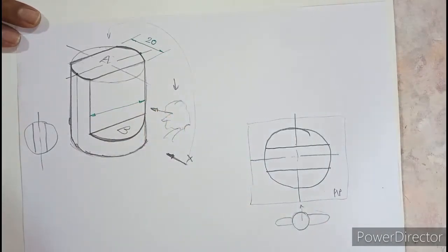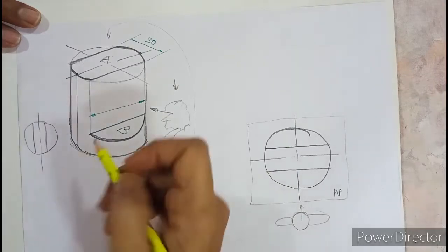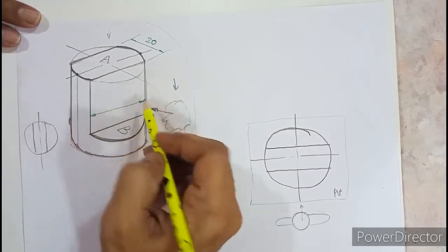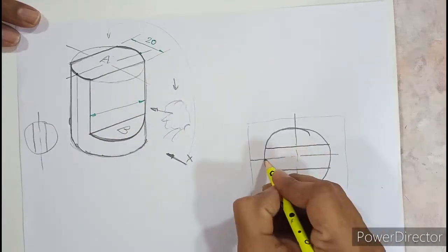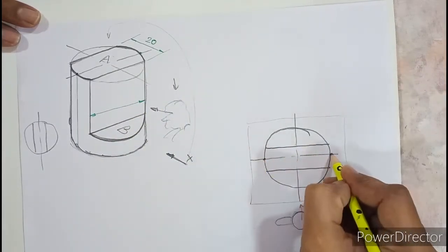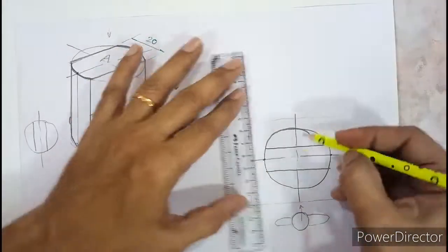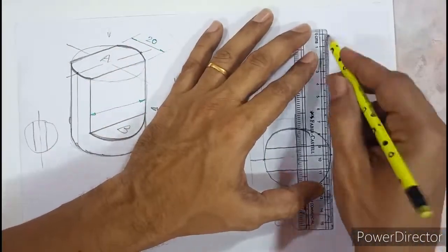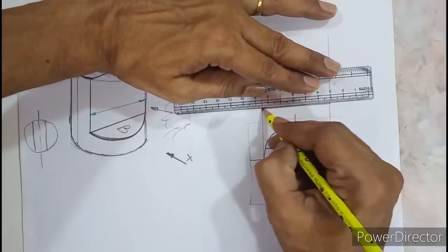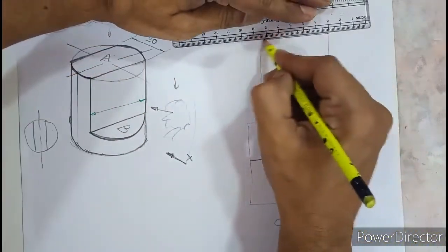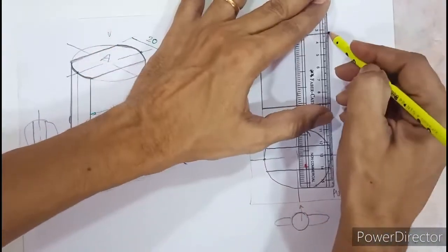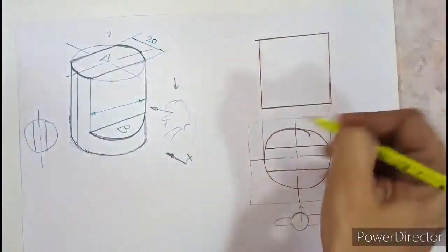Now let us draw the front view of this. So first of all, in the front view, this green line can be seen as the boundary of the cylinder on both these sides. So in this diagram, the boundary of the cylinder first and second is here. So when you project this up, you can see the boundary of the cylinder like this, and you can darken this. So now we are drawing the front view, which is always drawn on the vertical plane. So that is how the front view rectangle is drawn.